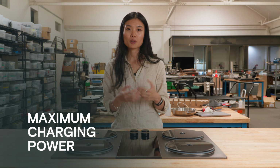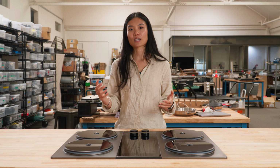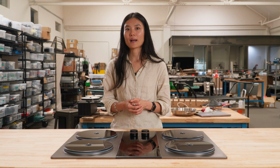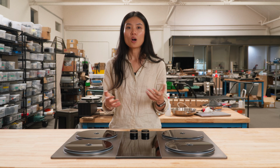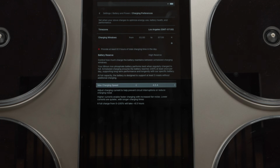You can also choose your maximum charging power. A higher charging power recharges the battery more quickly. Lower charging power reduces the electrical demand while charging and may also reduce charging fan noise. This can be useful if your home has limited electrical capacity or you'd simply prefer quieter charging. You can reduce the charging current as low as 4 amps.